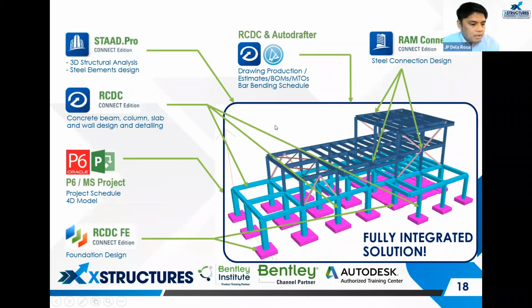And then, if you do have the project schedule written in Primavera P6 or MS Project, you can simply use the Structural Synchronizer of Bentley together with another software called ProStructures. You put the schedule and the direct STAAD model into ProStructures, and you can build your schedule simulation or the 4D model. The last part of the presentation, I'm going to show you how.